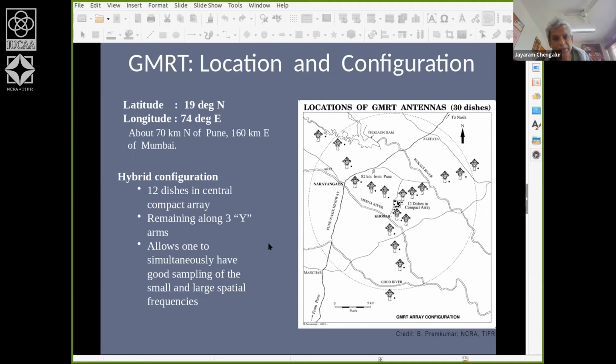So that kind of thing is manageable in a short distance, right? Within this 1 kilometer area, the antennas are put down in a semi-random fashion, and each one has a separate cable trench running to them. But because the distance is relatively small, the cost is manageable. And similarly, the exact location of these antennas on the ground would be determined by where is the nearest road, where is the nearest access point, and so on and so forth. So both of these considerations go in.